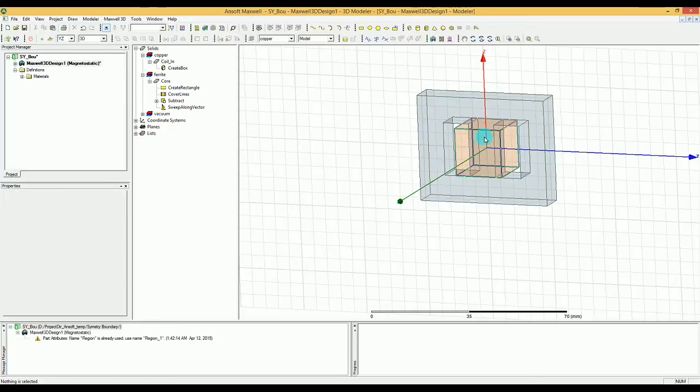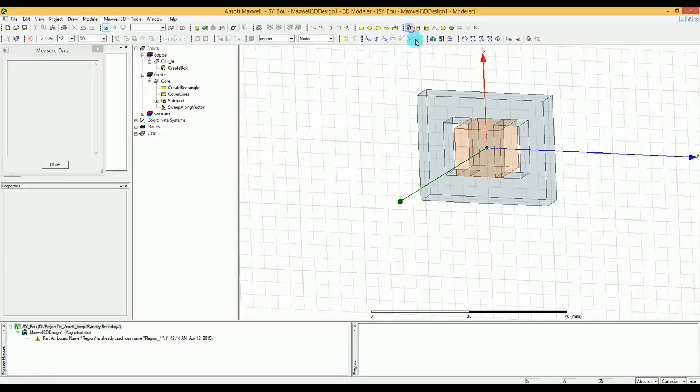Now what we can do is create another box, and subtract the core of this box and create kind of a coil by subtracting another box in the middle of that. So you just go and create another box, and I'm going to give you the numbers for that. -6, -6 and -9, and for dx, dy and dz we have 12, 12 and 18.